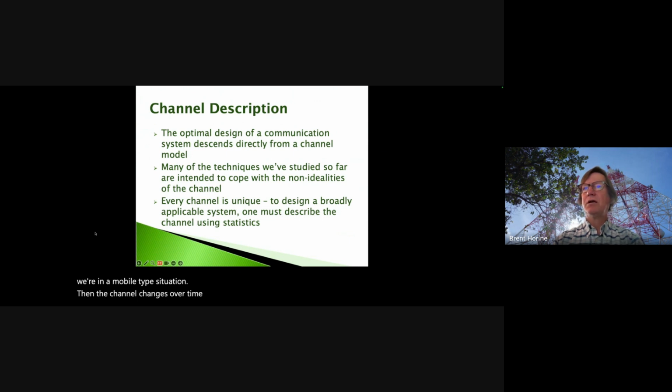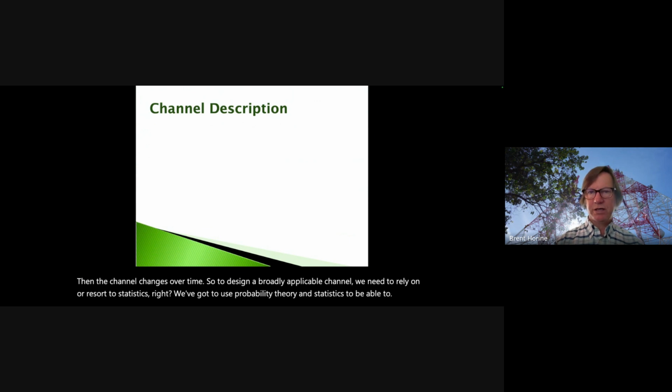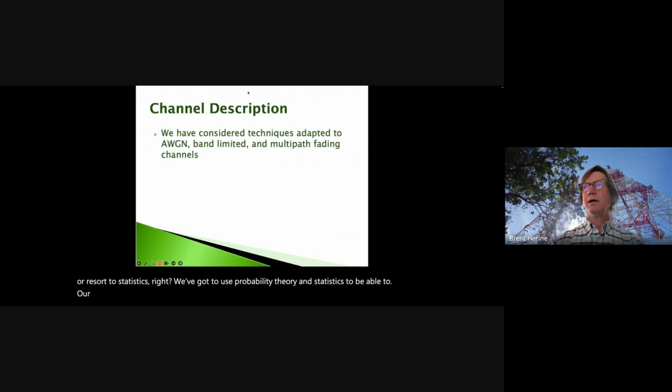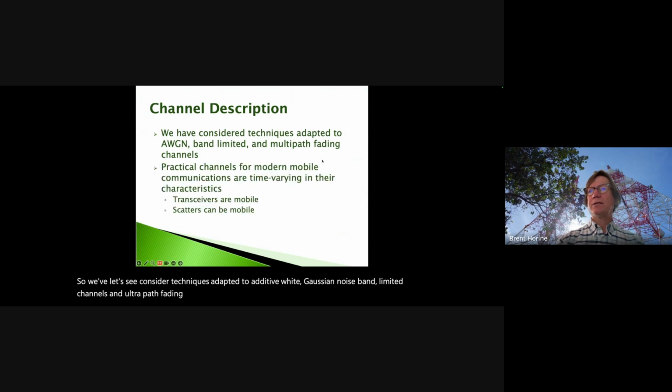So to design a broadly applicable channel, we need to resort to statistics, right? We've got to use probability theory and statistics to be able to model our channels. So we consider techniques adapted to additive white Gaussian noise, band limited channels, and multipath fading channels. Practical channels for modern mobile communications are time varying in their characteristics.